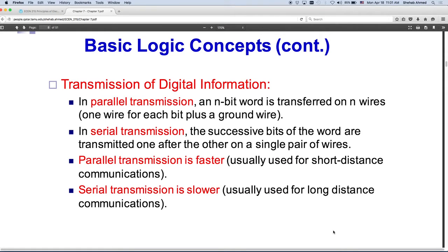And our computers have a combination of them. Our computers have certain signals that they exchange that are parallel, and certain signals that are serial. The USB, for example, is a serial bus. The processor's memory interface to your RAM, for example, may be parallel. That needs to be very fast, versus your mouse control. So what? Nobody cares about that. You're not anywhere close to how fast this computer is running.